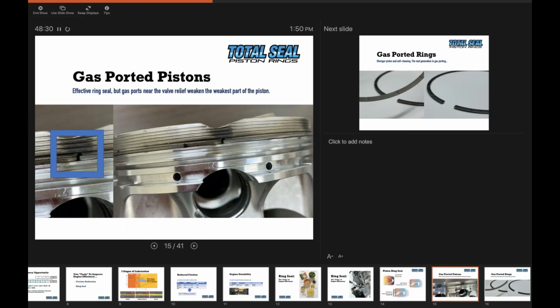That's the whole idea of gas porting. Been around since at least the 70s, and started off as vertical gas ports. And of course, the problem with vertical gas ports is that they get dirty. Gasoline is a blend of molecules. So there's a distillation curve with gasoline because it's a blend. There's small hydrocarbons and there's large hydrocarbons.